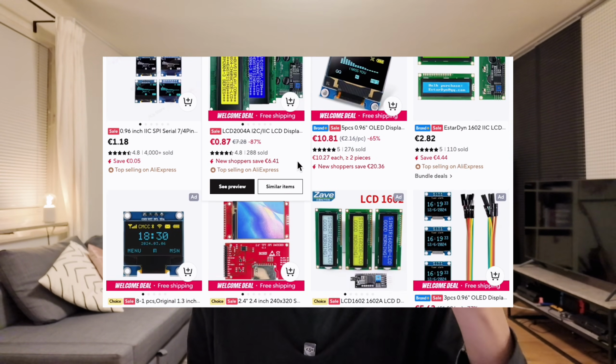I decided against it. It will draw more power and it will take more space. So it would make the device thicker and more expensive. It means adding a step during manufacturing. So it's an additional component that needs to be picked, put in place, and it will have a connector that will go into the PCB. And every step in the manufacturing process will add cost and complexity and things that could break or go wrong.